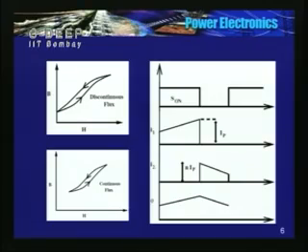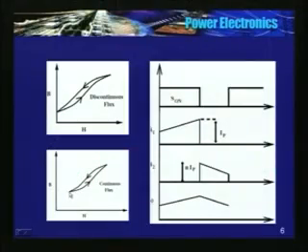Now you see here, accidentally D has increased. It implies that most of the time the switch is closed. The current increases linearly. It had a finite value, the current increases linearly, and since D has increased, the switch is closed for most of the time. It may so happen that the core will saturate.